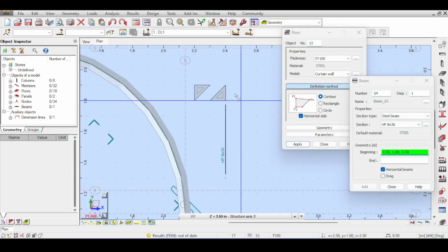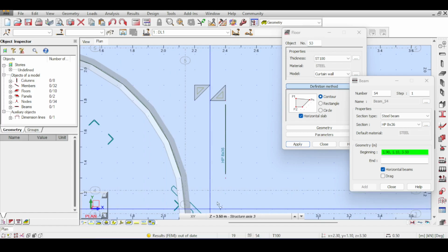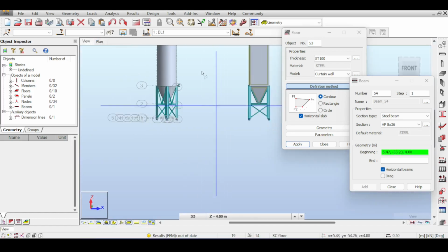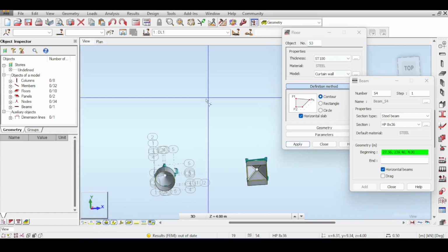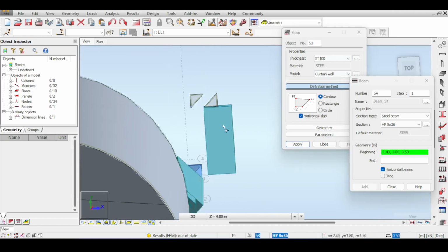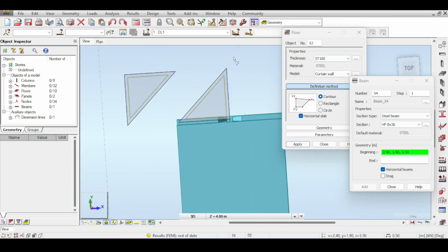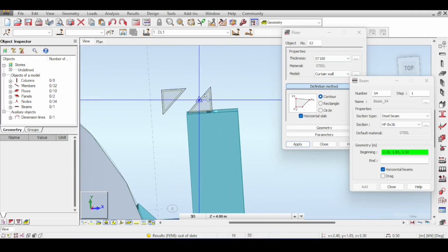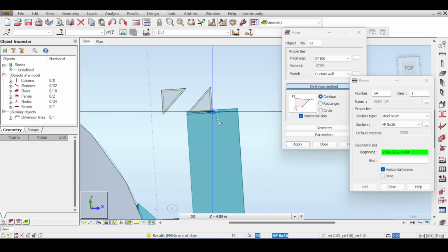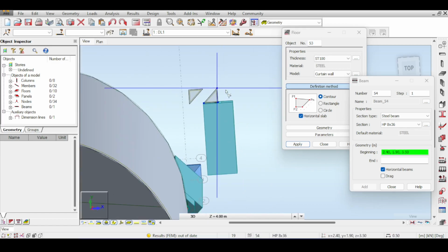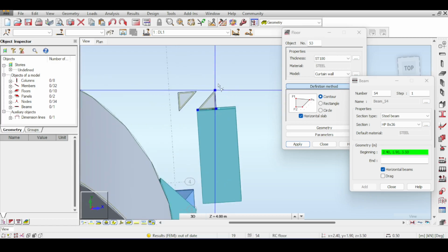So I'm planning something like this. The column connects to the hopper. Sorry, the column connects to a triangular shell element, and this shell element transfers the load of the column to the hopper. This is my plan. And this should mimic the little bracket you saw in the PDF file I have sent to you before, where you have seen some pictures of real-life silos. So that's the plan. And how do you do this?